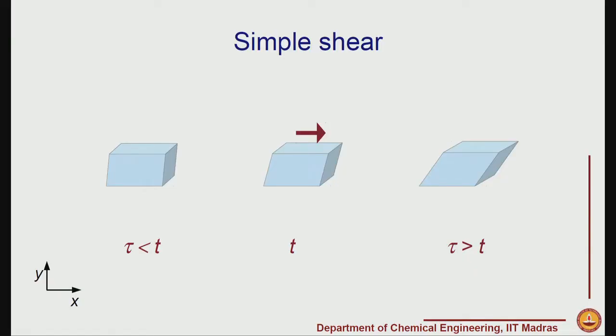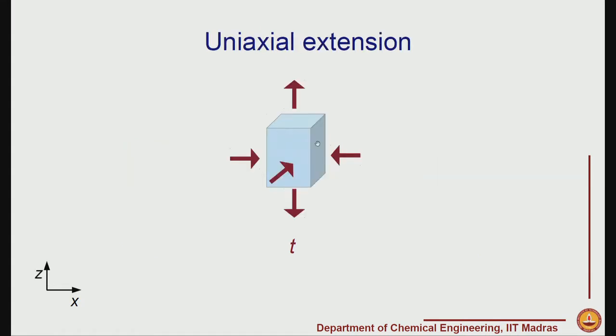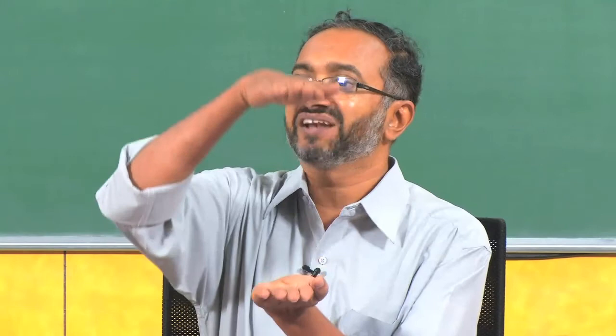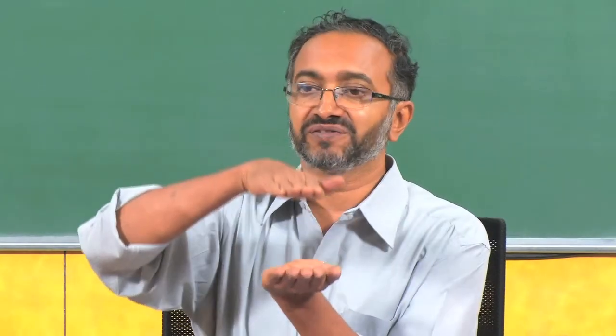So, which means we will have to either do a constant shear rate, and constant shear rate will be automatically specified if top velocity is fixed, and similarly here constant rate will be specified if the position of the plate changes exponentially in time. The rate of the plate motion is constant. So, therefore, in terms of position control it is far more difficult. When plate moves with a constant velocity, position changes linearly with time. Actually, how we will achieve this is take the fluid between two plates and then separate like this. So, therefore, position of the plate is also changing.